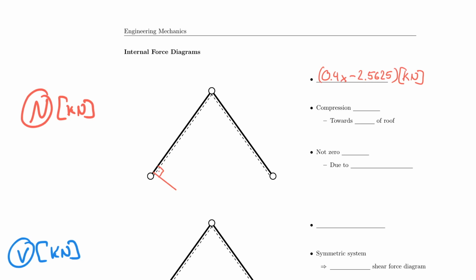And so now I can actually plug in values to my equation here. I can plug in 1, 2, 3, 4, 5 until I convince myself, or I can understand that there's load pushing here, there's more load pushing here, more and more and more. And so therefore the normal force, the compression, gets more towards the bottom of the rafter. And therefore I have to have a slope that decreases towards the top, if you will. So it goes from here to less internal force. And so all I need to do is plug in 5 and then connect my values.